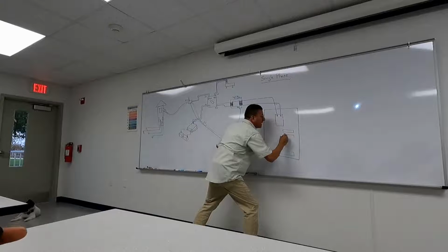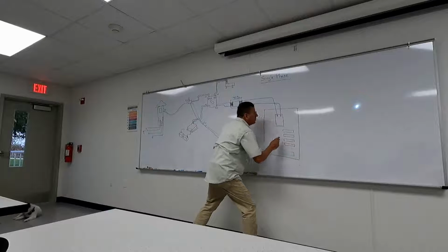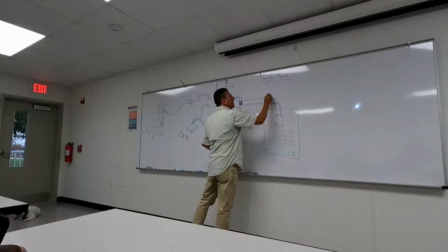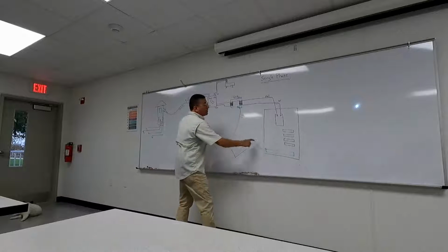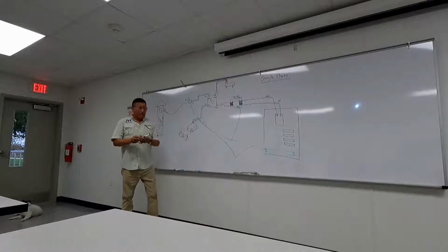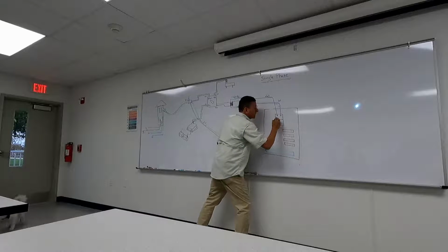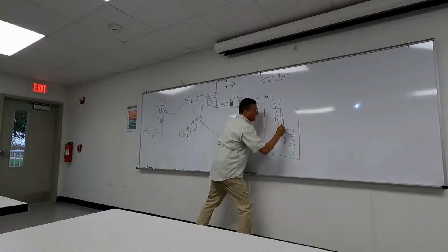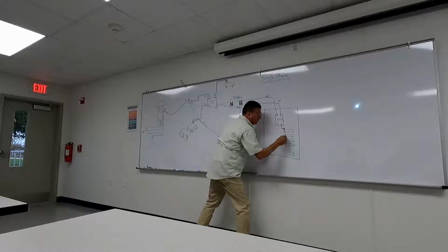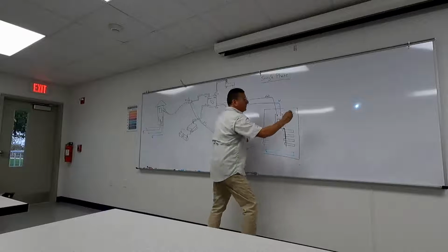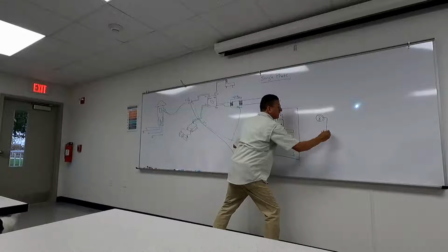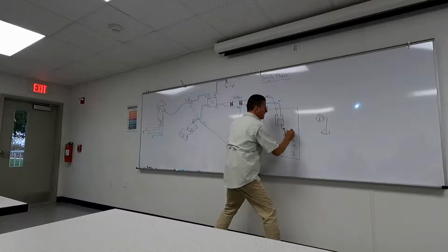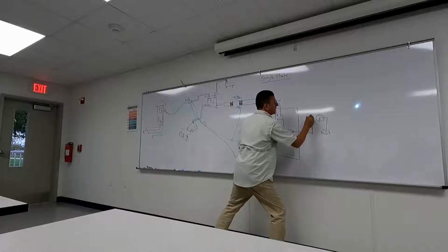In this particular case, what happened with the breakers? The breakers are, all of them, single phase breakers, because I only have one phase. And this is neutral, and ground is here. And this is the main breaker. And one hot line is coming here to connect all the breakers. And in the output, for example, I am going to connect one fan. The fan is 120, okay. The hot line is coming here.